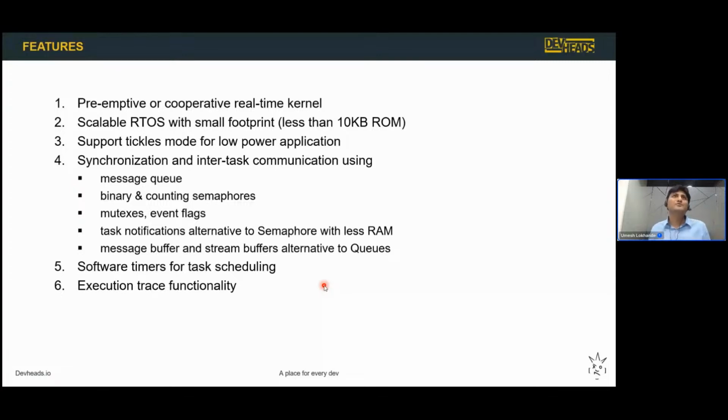And I'm going to show you today with a live example how you debug an RTOS application. We are not going into RTOS-aware debugging, but of course this debugging will show you how you can trace the state of a task, which one is running and which one is in ready state. The task has a state, so we're going to talk about it in the future slides, but I think now it is clear that these are the features that FreeRTOS has to offer, and that's the reason why it has become a preferred choice for anybody who gets started with a real-time operating system on a microcontroller or processor.